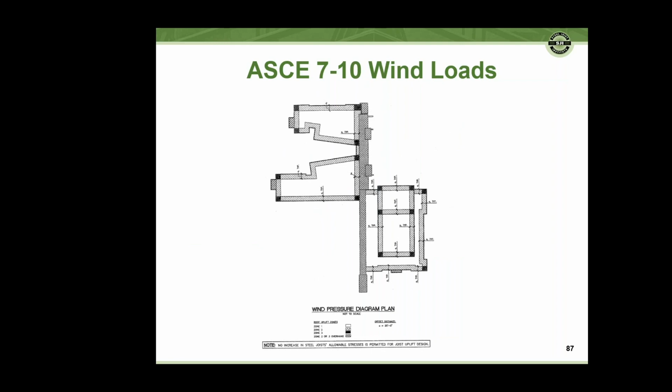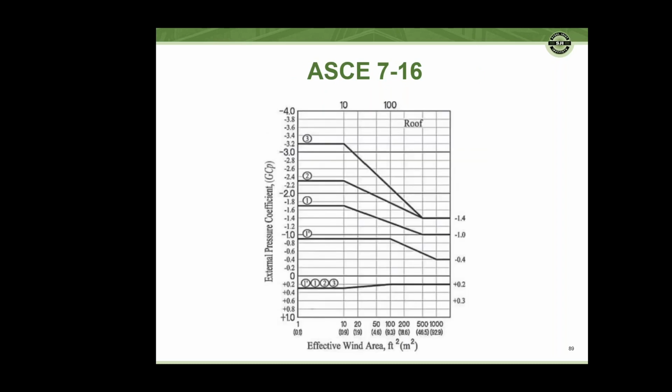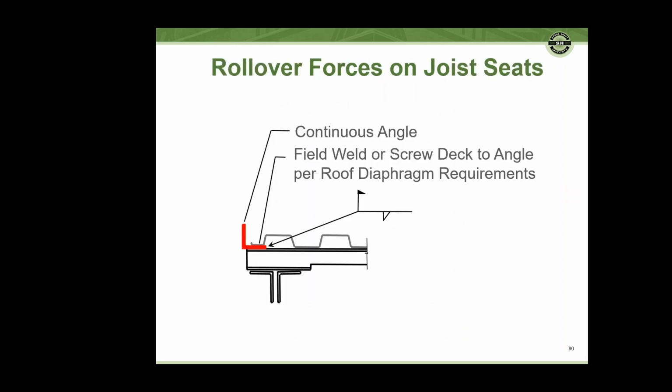complicated in and of itself. If you've got just a sample roof framing plan here of how busy it can be, it's about to get a little worse. So ASCE 7-16 adds an additional zone, or edge zone if you will, and the corner now becomes L-shaped, and so the charts and loads become more complicated with ASCE 7-16. I say more complicated, just busier, and something to be aware is coming.